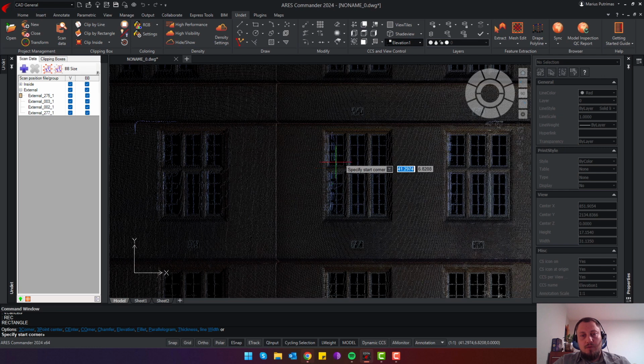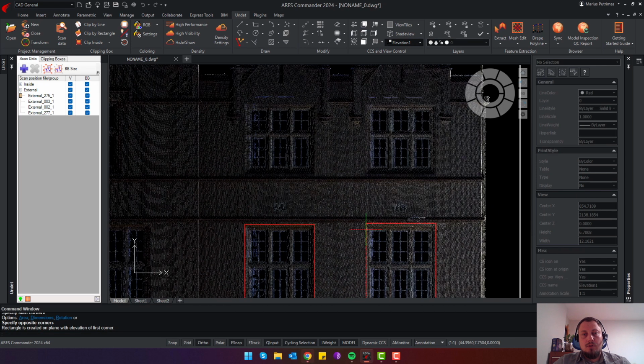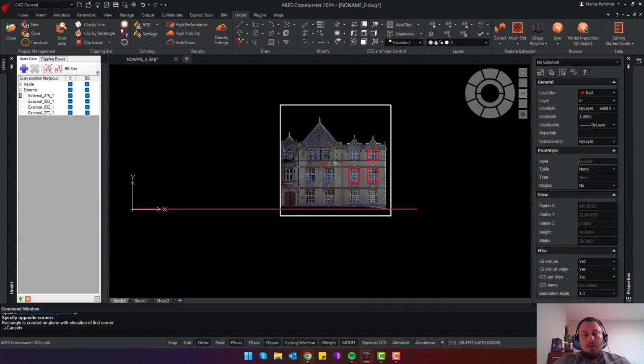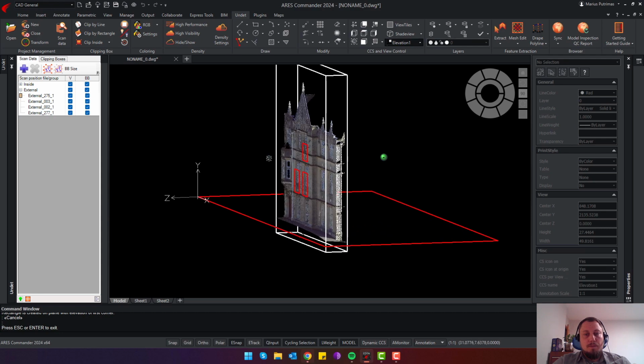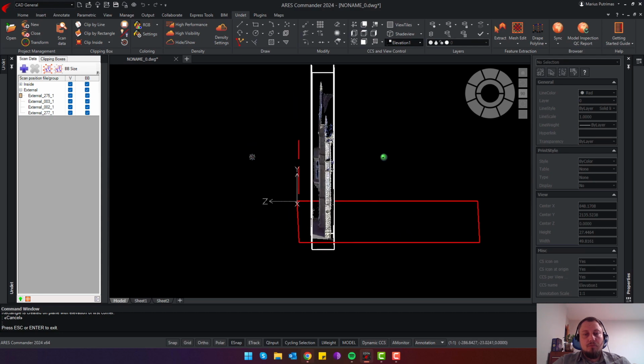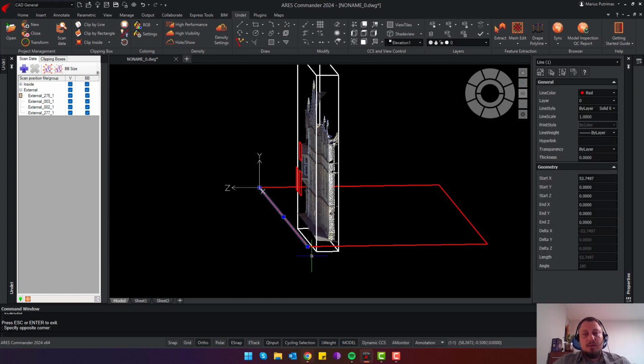And if I vectorize the window openings, not very detailed, just to show how my UCS is looking, and if I rotate this view, you will see these two window openings are on my new UCS plane. And this line is a datum line. And if I go back to the old coordinate system, this reference line will show the 18 meters of the global point cloud level.